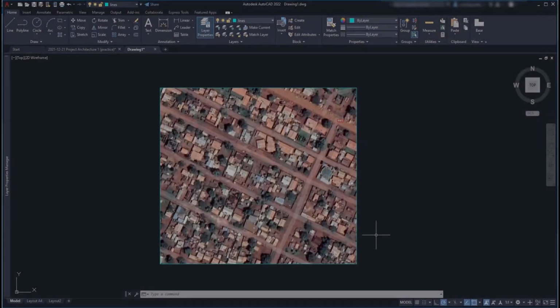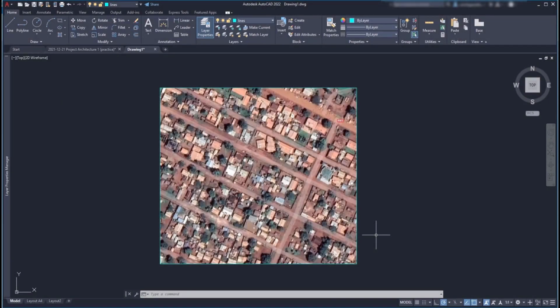Insert a field in a text. This is a very interesting and useful advanced option available in AutoCAD. A field is basically a way to insert data that we expect to change during the life cycle of a drawing. This is actually the definition that you can see on the Autodesk website, by the way.